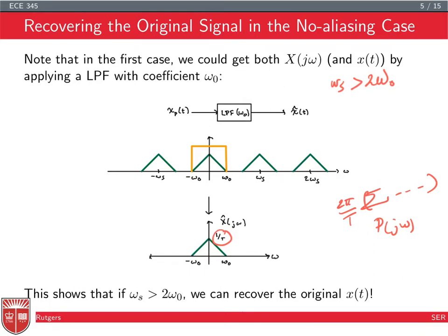And this is really amazing because out of discrete samples, I could recover the original signal by just doing a low-pass filter. All I have to do is sample at a frequency larger than twice the maximum frequency of the signal, then make the discrete signal go through a low-pass filter, and then I can recover the whole analog signal.